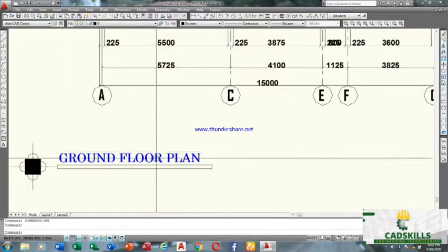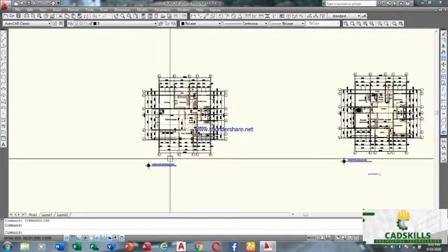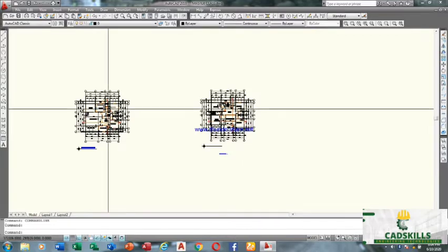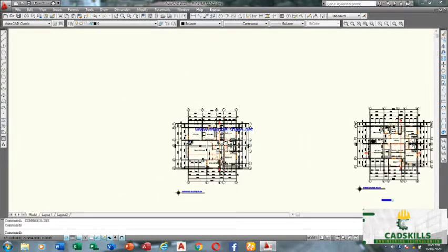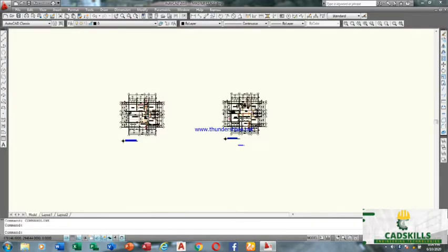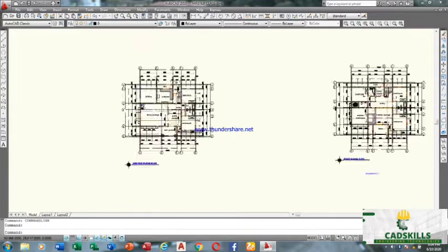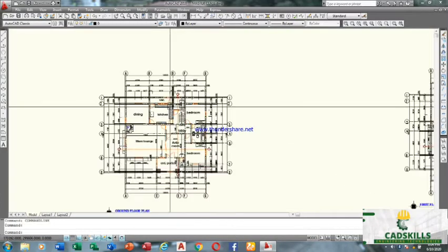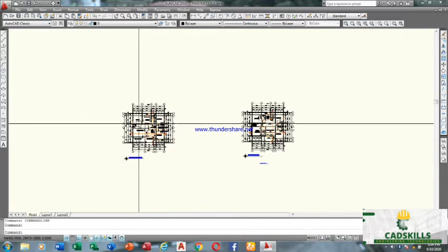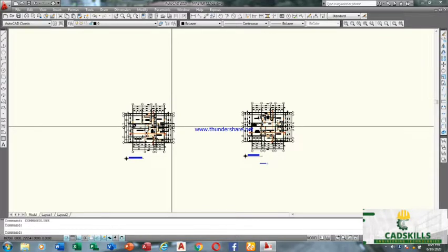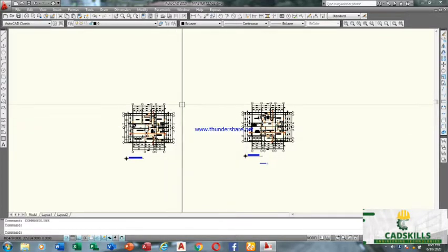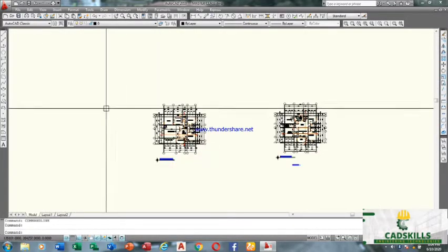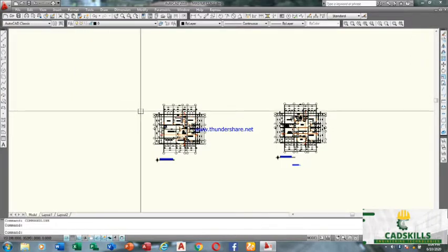The drawing you are seeing is the drawing we'll be making use of in this our design class. We start by looking at the drawing, understanding the concept of the drawing. After that, you have to remove all the dimensions of the drawing. You open the drawing, you check the alignment of the ground floor with the first floor. You position everything. Make sure that the alignments are together. Know where that is matching and where that is not matching.